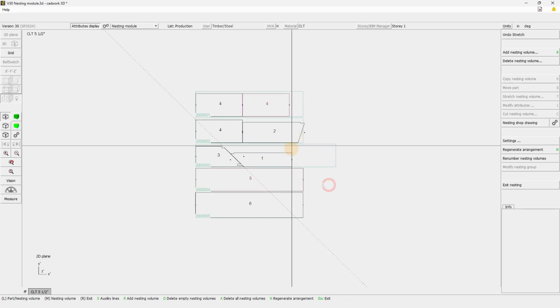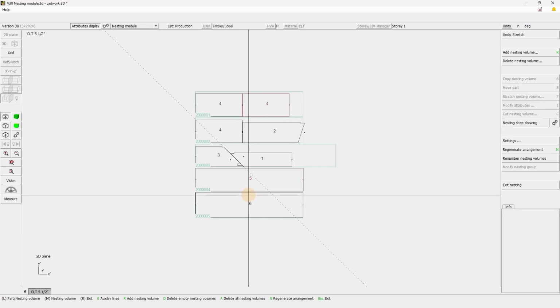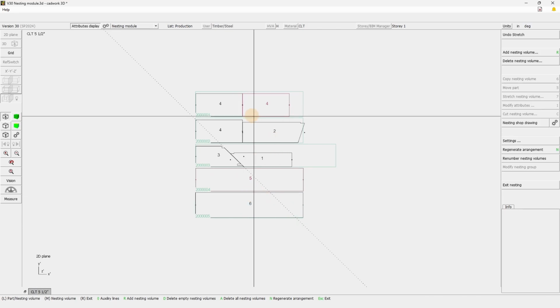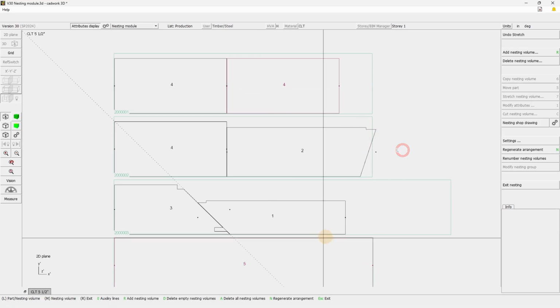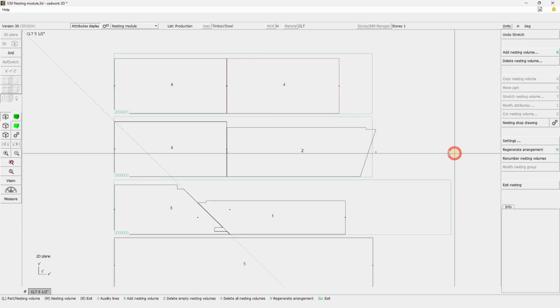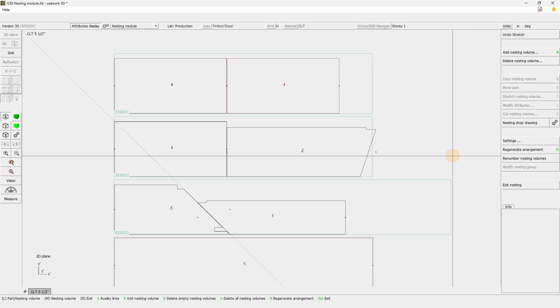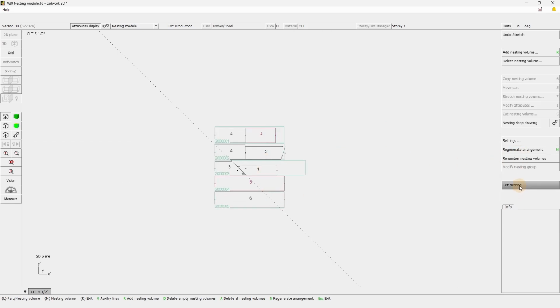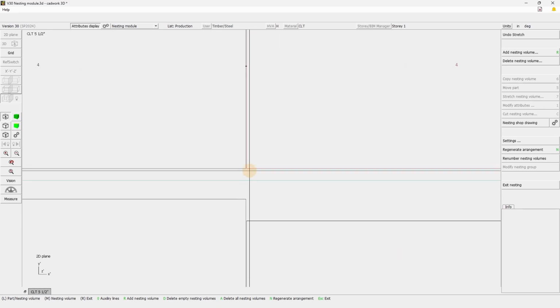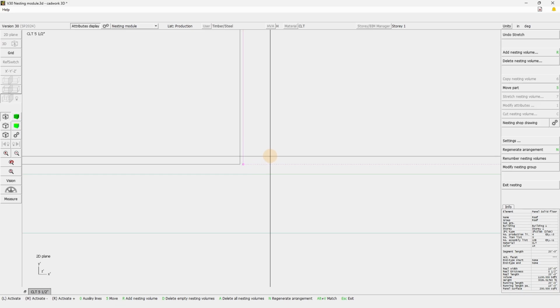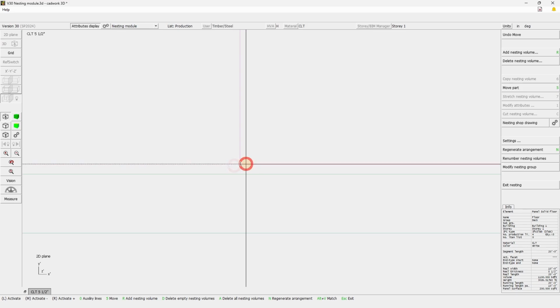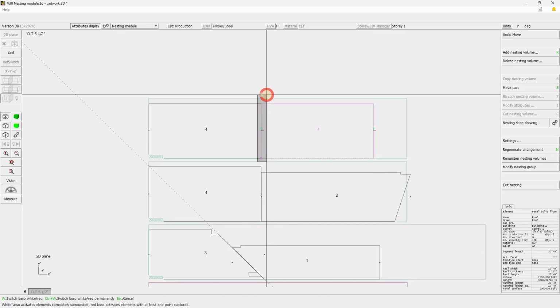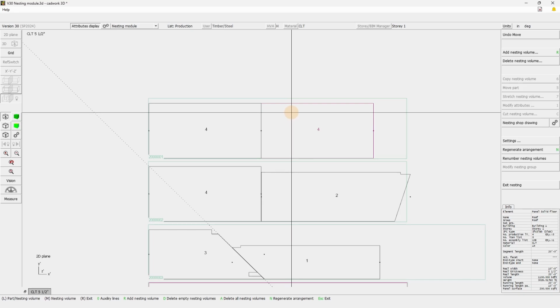So now that we have all these elements, what can we do about the current result? Of course, here we have some elements sticking out, too much leftovers. So how can we actually adjust, stretch, or basically change these nesting volumes? One thing here is if you try to get out now, knowing that you have some element sticking out, or even some element that could be considered as colliding. So here I'm just going to force this. If I use Shift and left arrow key, these two elements are now actually touching each other, meaning that it's actually impossible to create that cut. This is what we will consider to be actually a collision.